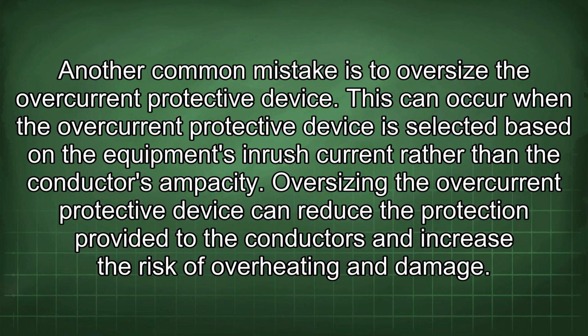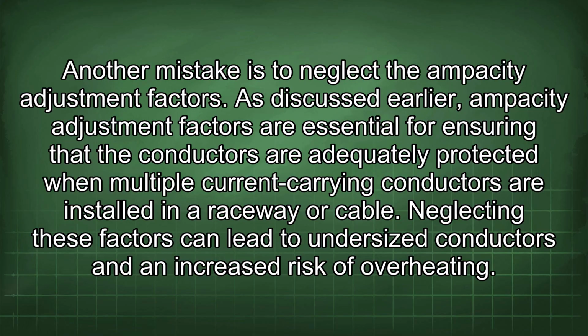Another mistake is to neglect the ampacity adjustment factors. As discussed earlier, ampacity adjustment factors are essential for ensuring that the conductors are adequately protected when multiple current-carrying conductors are installed in a raceway or cable. Neglecting these factors can lead to undersized conductors and an increased risk of overheating.